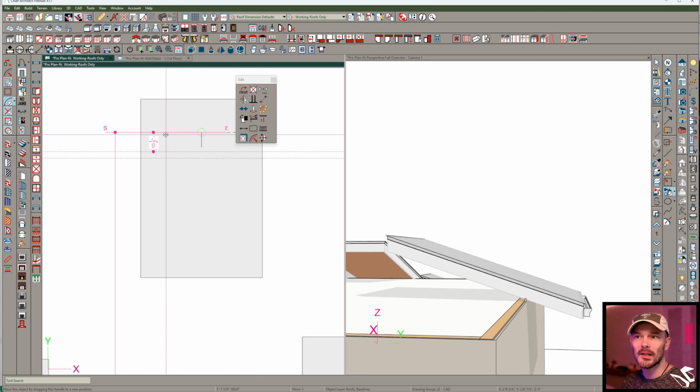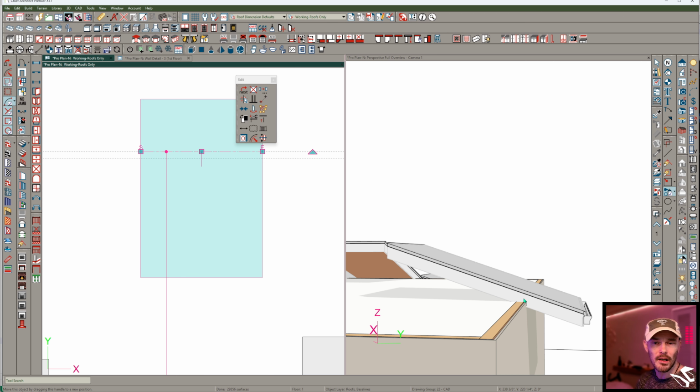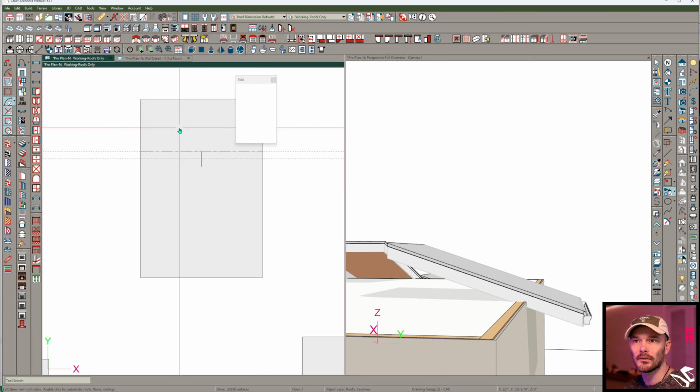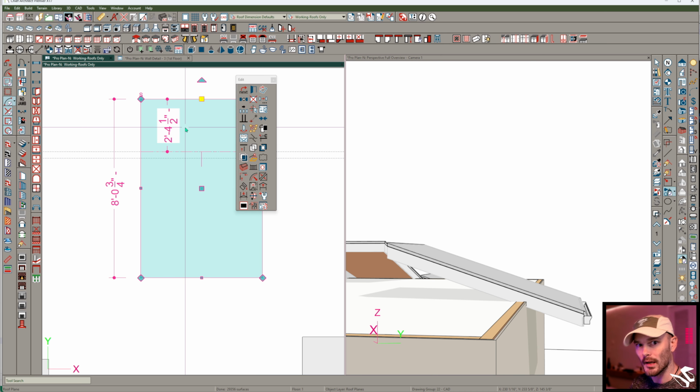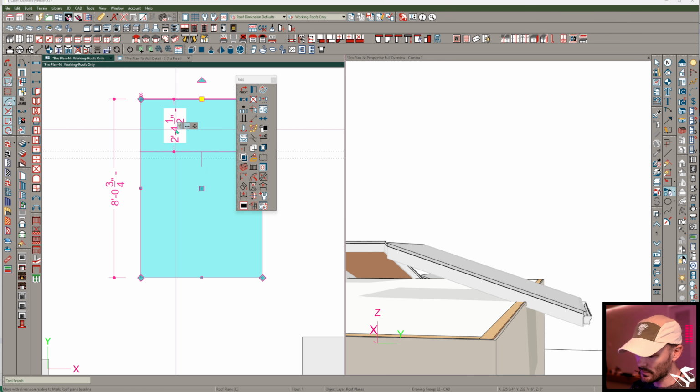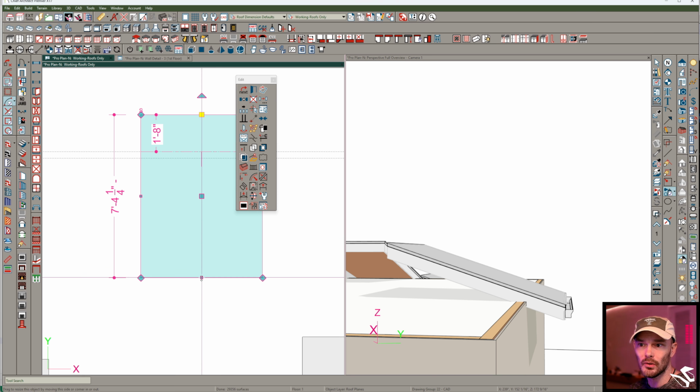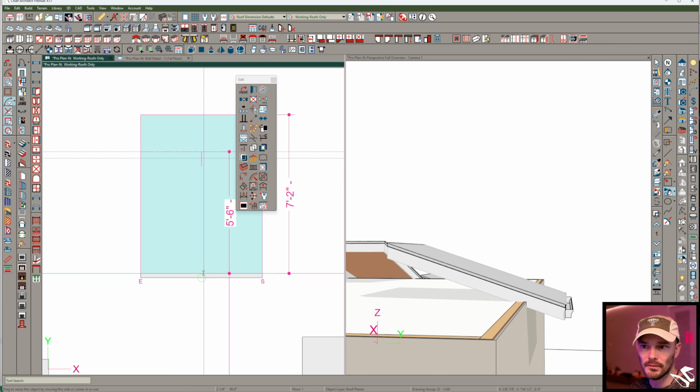So what happens when I just drag this baseline back, snap it right to that main wall layer? Watch what happens. We get that seat cut back. That's correct. So effectively, we've just changed the overhang of the eave. Alternatively, you could have just come in here, punched in what your eave overhang is, and if you needed to move this in a corresponding way, you would just drag this edit handle.